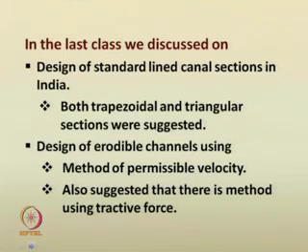In the last class, we discussed the design of standard lined canal sections in India, both the trapezoidal and triangular sections, and how they have to be designed. We also briefly started the design procedure of erodible channels. We introduced the concept of the method of permissible velocity. We also suggested that there is a method called the method of tractive force to design erodible channels.